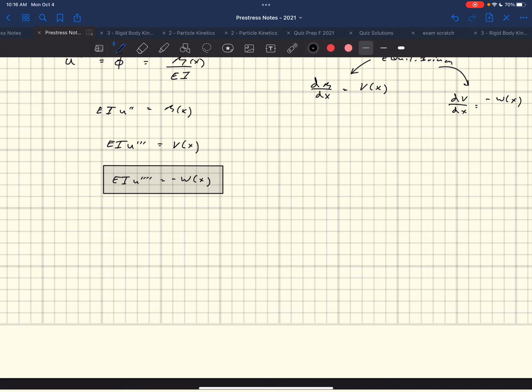So you have a fourth order differential equation, so you have to set 4 different boundary conditions, and it'll be like the deflections and rotations at one end, and then the moments and shears at the other end, and you set those things and you solve, and it gives you u as a function of x. I think it's a very robust way of solving it. You cannot do nonlinear, but you could solve indeterminate structures and all that stuff with this equation. And again, it's the fundamentals for beam elements and finite elements. This is kind of cool.